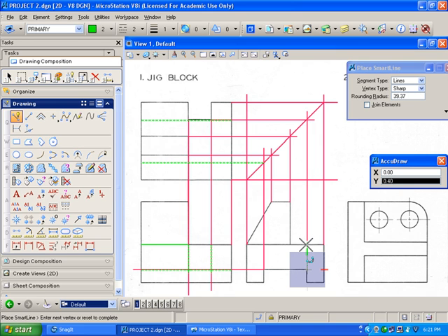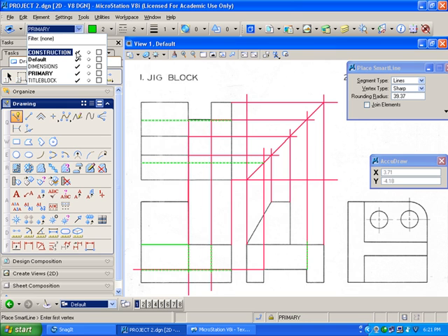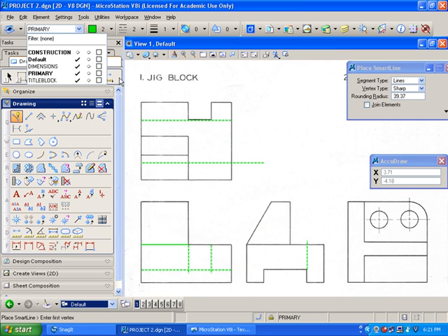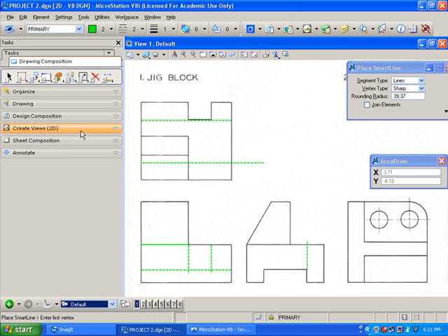So let's turn off our construction lines now. We can just come up here and click on this check mark, and we're going to start to see where our lines are hopefully going to start making some sense. We need our tool to extend these ends, so we're going to use our drawing, right here, modify elements, go down to extend a line.